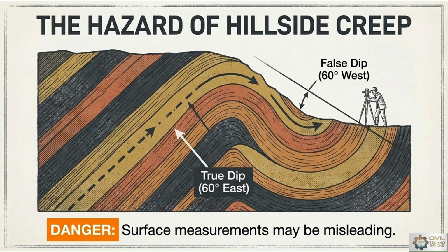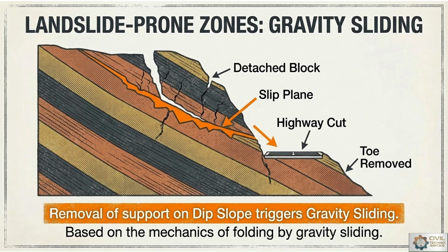Landslides occur due to weak geological formations, heavy rainfall and improper slope cutting. So we have to complete the survey activity based on those criteria. Geological investigations help identify unstable slopes and potential failure zones below the subsurface. Retaining walls, rock bolting, and drainage systems are all methods used for soil stabilization or slope stabilization. Landslide-prone zones are where gravity sliding is there.